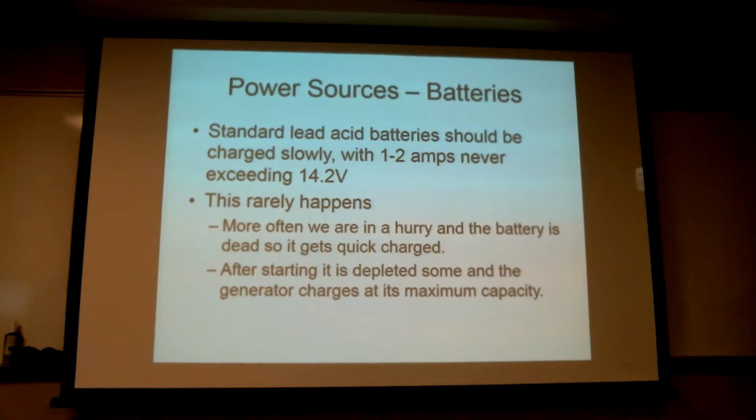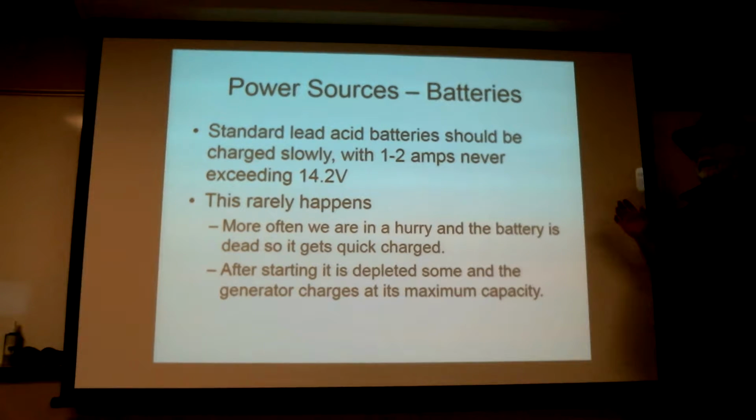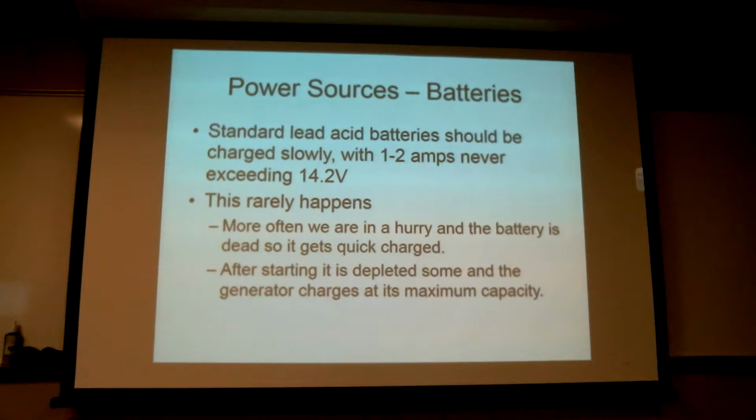The other thing that happens is as the battery gets really depleted, its internal resistance starts going way up. And it goes to the point that it's so high it'll almost not take a charge. I found really severely depleted batteries, sometimes you have to throw them on a high rate of charge, high voltage, and let them sit for a couple of hours. You gotta watch them kind of closely. Then all of a sudden you'll see the current start to go, then turn it way back down.